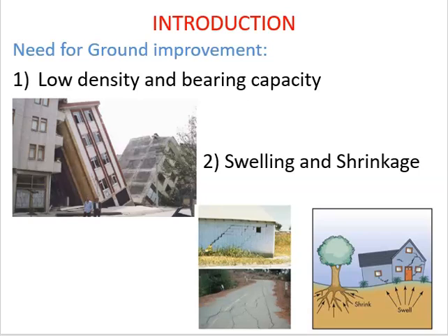First point is low density and bearing capacity of soil at the site. If the soil is loosely deposited sand or under consolidated clay, the density of the soil will be less. As the bearing capacity of the soil depends on density of soil, even the bearing capacity will be less for low density soils. Foundations constructed on this kind of soils will be subjected to either bearing capacity failure or settlement failure.